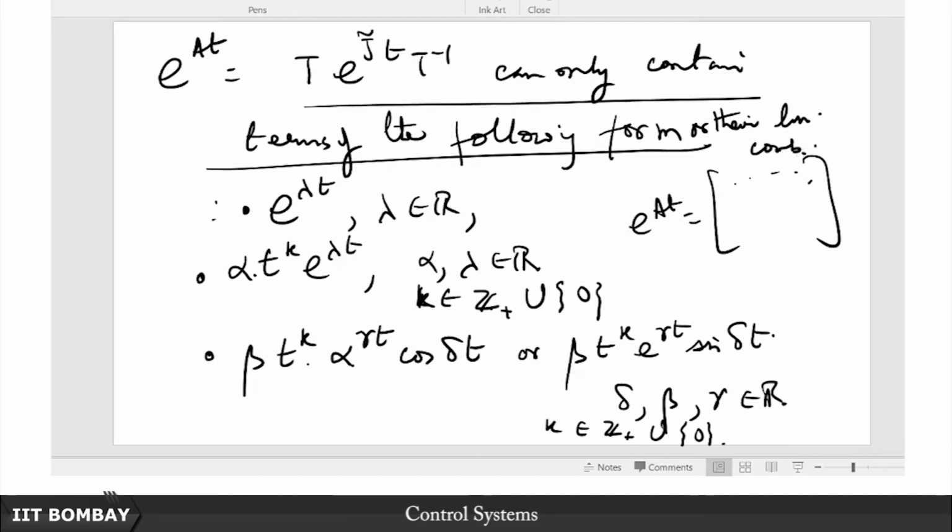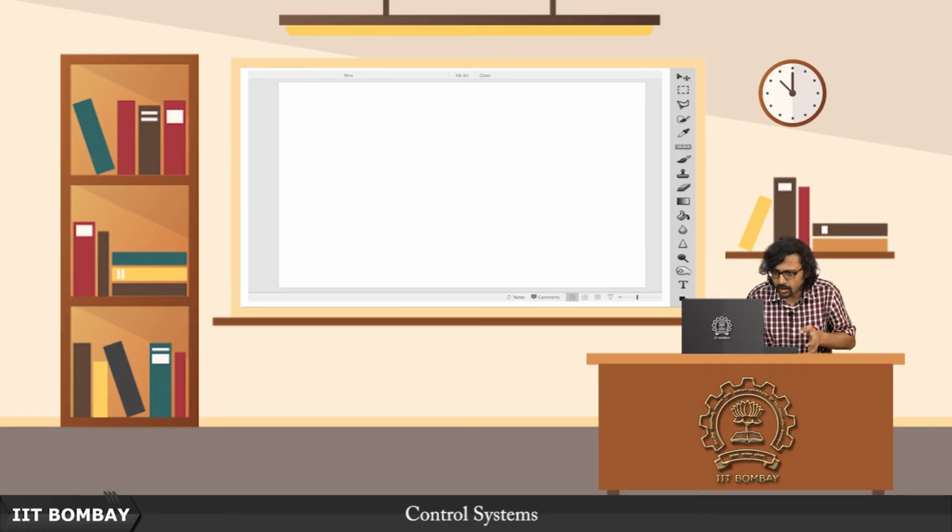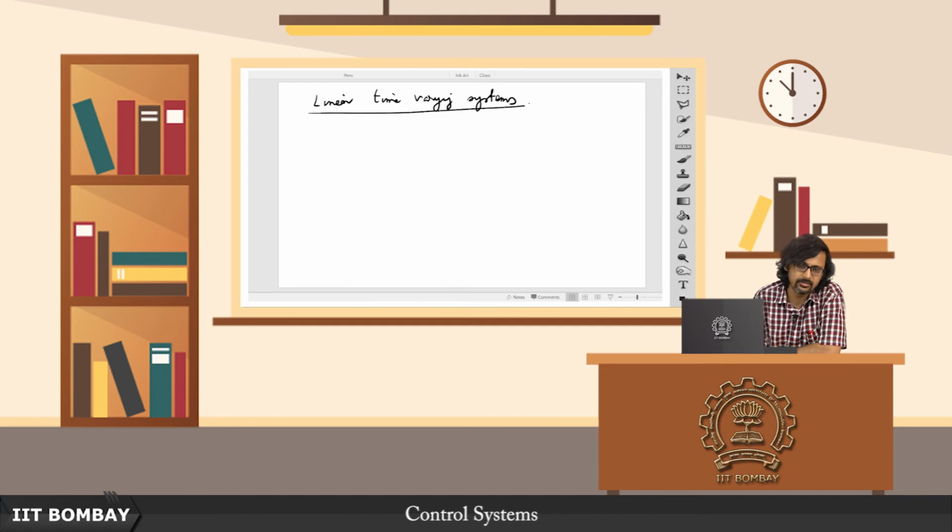So that is all we wanted to discuss, and now in whatever time is remaining in this lecture and probably a part of the next lecture, we shall be focusing on a brief journey into linear time varying systems. Right at the beginning we said that in this course we shall only concern ourselves with linear time invariant systems, and that is when we introduced Laplace transforms and said that this provides us with a very beautiful handle. But now state space methods are not really limited to linear time invariant systems.